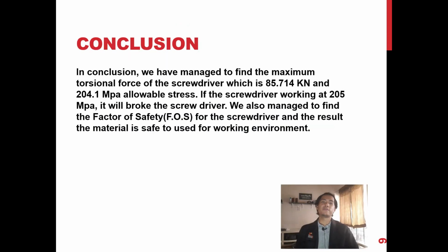For the conclusion, we have managed to find the maximum torsional force for the screwdriver, which is 85.714 kilonewton, and the allowable stress is 204.1 megapascal. Basically, if the screwdriver is working at 205 megapascal, it will break. And lastly, we also managed to find the factor of safety for the screwdriver, and the result shows the material is safe to use for the working environment. So that's all for us, and have a good day.